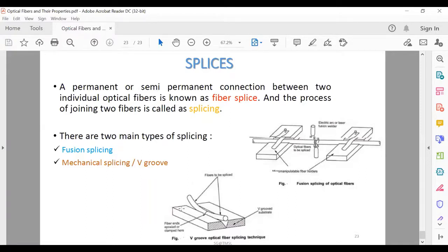Now the two types of fiber optic splices are used in different applications. The mechanical one is used for applications where the splices need to be made very quickly and where the expensive equipment for fusion splices may not be available. Some of the mechanical fiber optic splices are there for connection and disconnection purposes. So in this way, the mechanical splice may be used in applications where the splices may be less permanent.